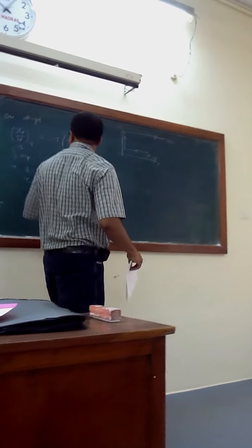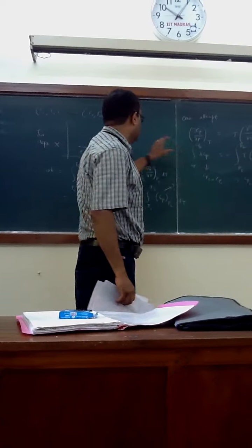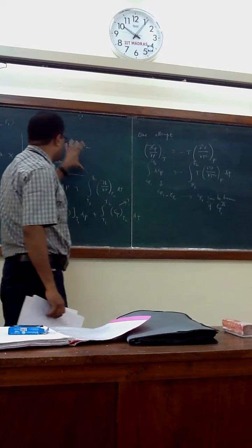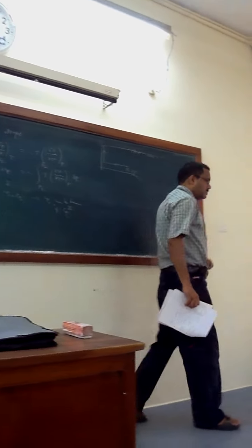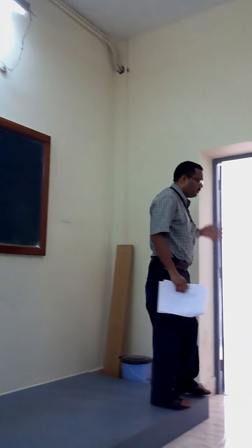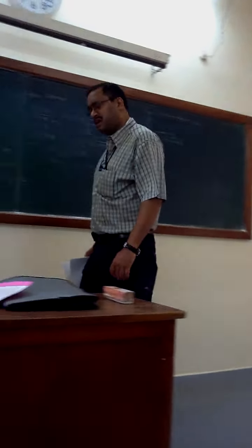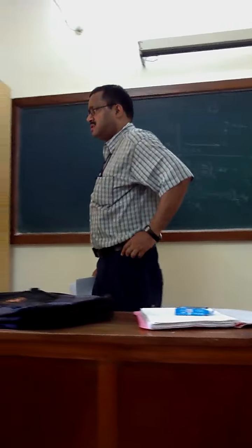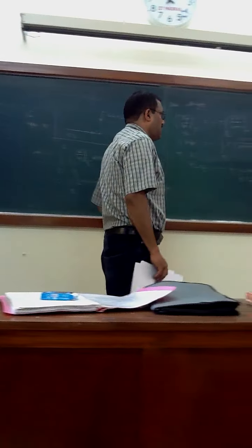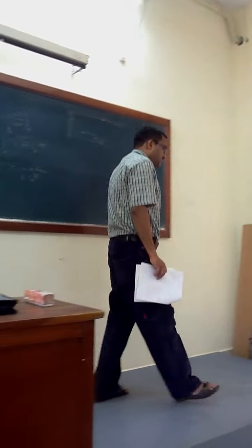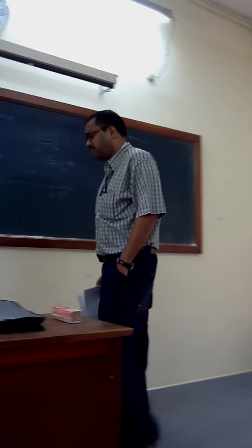The vertical step was the problem here. Very important point: the vertical step should be around P tending to 0, because that will give constant pressure and that will give Cp ideal gas at P tending to 0. Horizontal lines you don't care about. Only the vertical line you care about, because that gives directly a parameter like Cp.